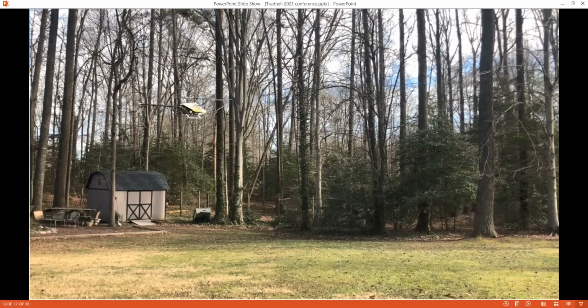This is good. What I'm doing here is, for the maximum gain where it finds that 180 degree phase point and that frequency, it then goes and tracks that 180 degree phase. So it works pretty slick, in that it moves with the 180 degree phase frequency and keeps it there while it's still checking to see if we're seeing any rise in the gain that indicates instability. So that kind of works. The thing that is getting me right now is that I could have other frequencies, like the lead lag regressive, and how I can check to make sure I'm not exciting that.